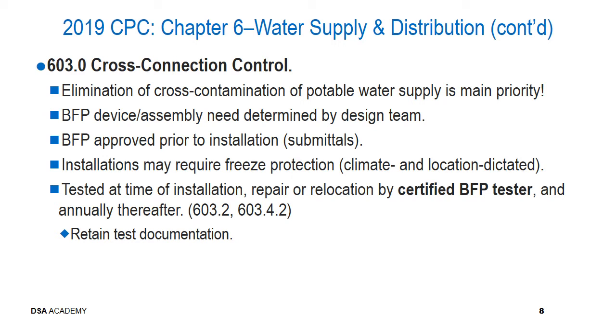The important thing to remember for a project inspector, again, is to, number one, make sure that the certified backflow prevention tester certification is current at the time of the test they perform, and also retain a copy of the documentation that is prepared by the certified BFP tester.